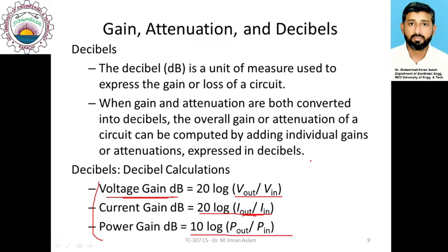We know that the power is actually related to the voltage squared. So this square is appearing here. You can see that the power becomes multiplication in logarithm. So if you multiply 10 by this 2, if you represent the same thing with voltage, this becomes 20.